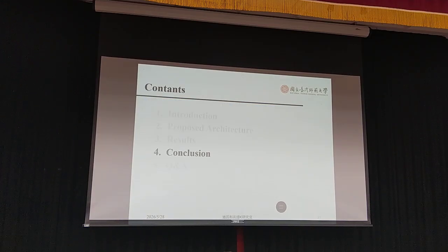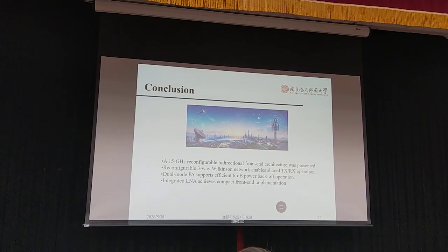Conclusion. To conclude, we present a reconfigurable bidirectional front-end architecture. The configurable three-way Wilkinson network enables shared transmit and receive operation. The dual mode PA supports dynamic power scaling and 6 dB back-off operation. Finally, the current reused low noise amplifier provides high gain with low power consumption.